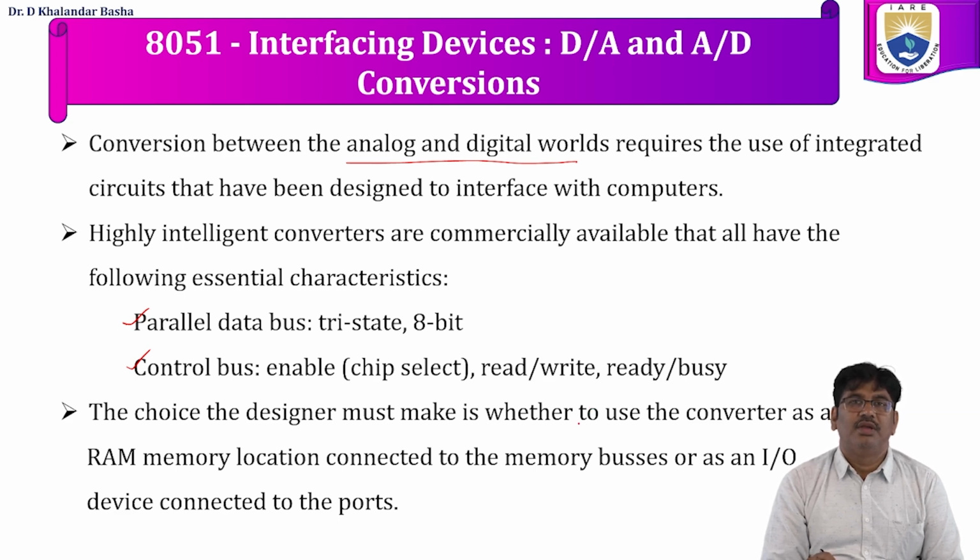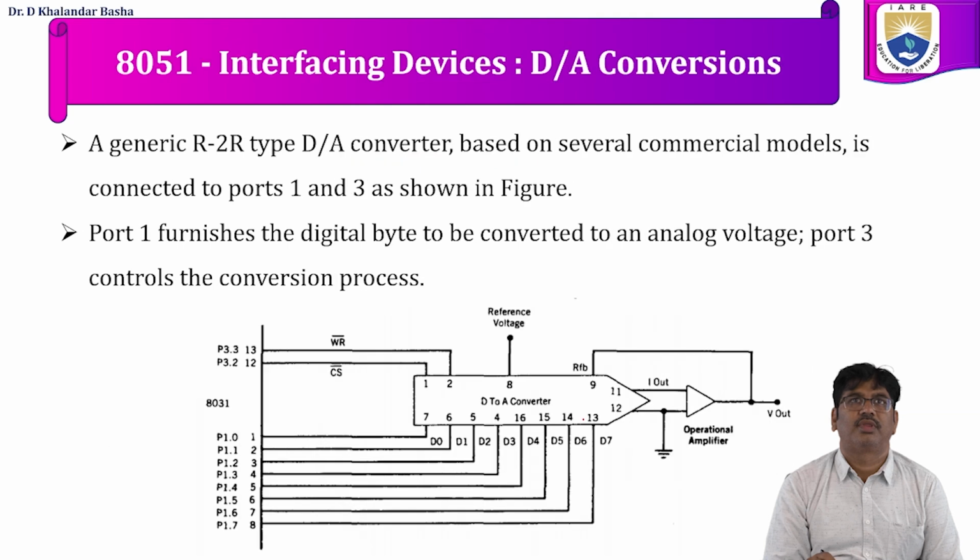The choice the designer must make is whether to use the converter as a RAM memory location connected to memory buses or as an I/O device connected to ports.